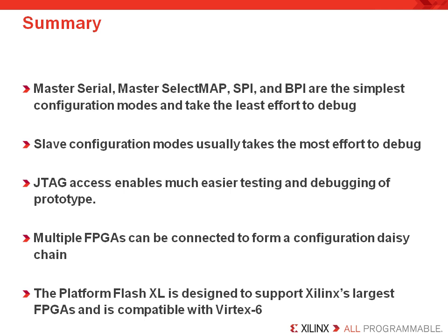The platform Flash XL is designed to support Xilinx's newest and largest FPGA families. It also includes a NOR flash interface that allows designers to store data and software with the FPGA's bitstream in a single flash component. Likewise, the platform Flash XL offers the fastest FPGA configuration rate through master SelectMAP mode. This makes the XL ideal for PCI Express and other high-end performance applications.